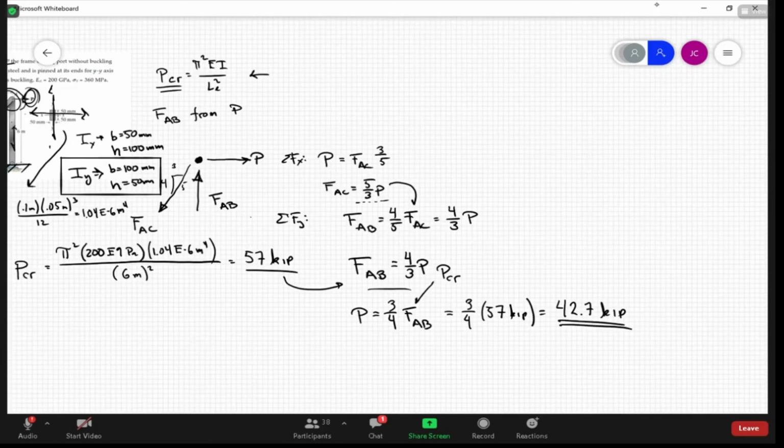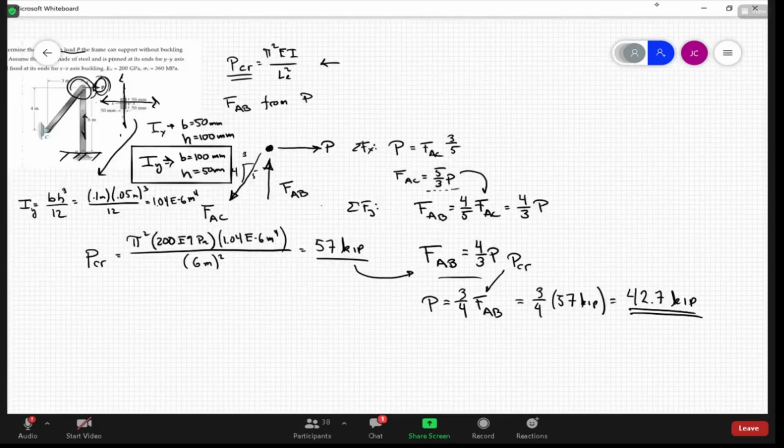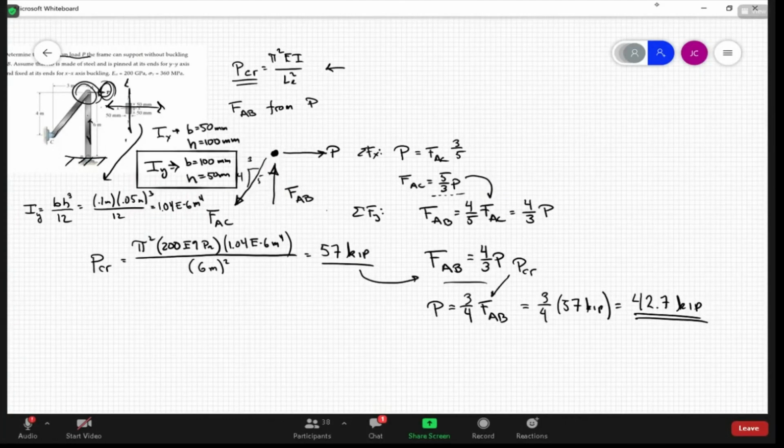And you could probably look at the stresses in the other elements. Depending upon the slenderness of these elements, it might fail sooner due to a force-over-area type of failure, the tensile failure, right? So whenever you see structures that are in compression and they're slender, a light bulb should go off in your head and you say, look, I've got to worry about buckling. Okay. So you have to go through all your other analyses. Does it fail due to bending? What's the combined loading stress in it? All that sort of stuff.